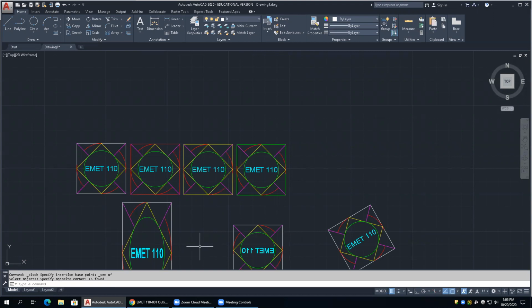Originally, I used the center. So when I redefined it, I still want to use that center. The original block I used center, and I need to use the same center point for the redefined block. If I don't, they're not going to correlate. No, the center of the new one. Yeah, the center of the new one. You pick the center of the old one, that difference is your X and Y displacement, so move by that amount. Okay.